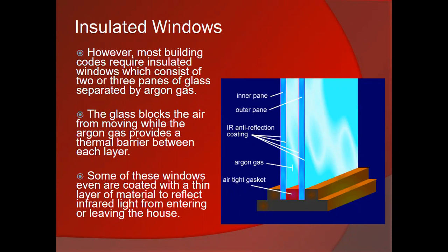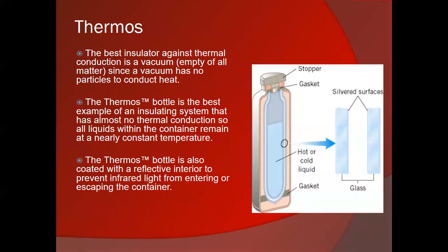Now, glass is too good of a conductor of heat to be practical in the single pane. So what we actually do now is we create windows. Look at some of your windows sometime. If it's a recent construction, they'll put a little air gap between two plates of glass. And this allows a thermal barrier that prevents the heat from easily coming in and out. In fact, in really good windows, there'll be triple pane windows, and those are much better at retaining the heat.